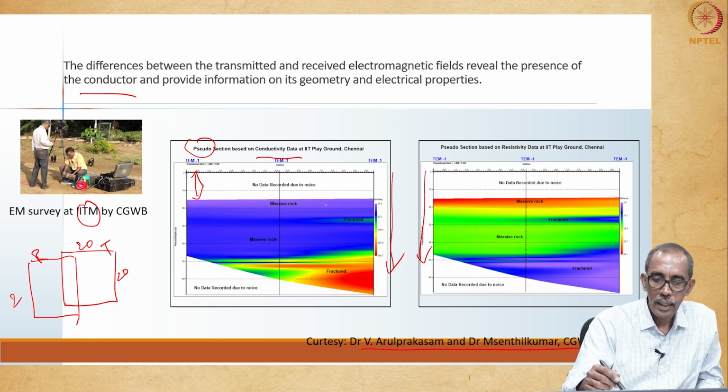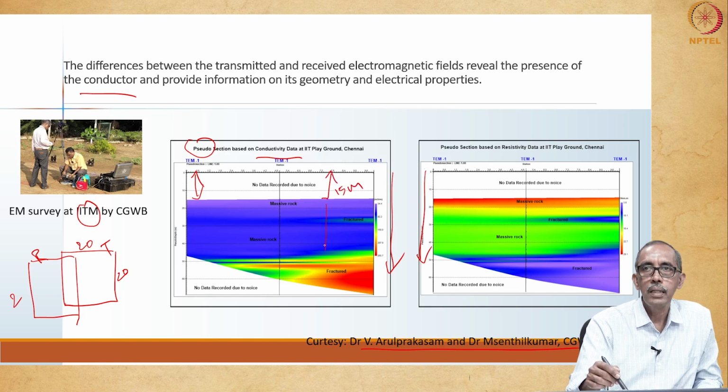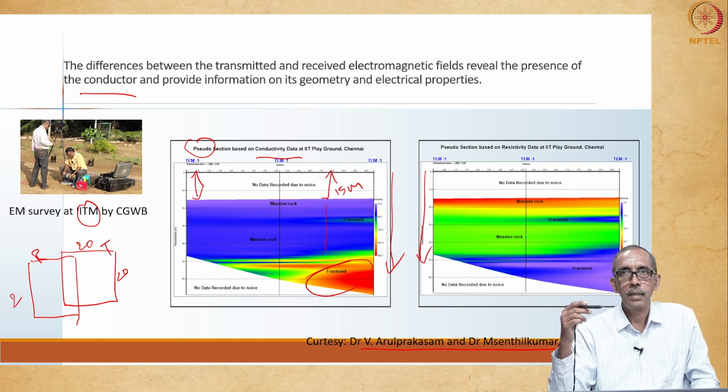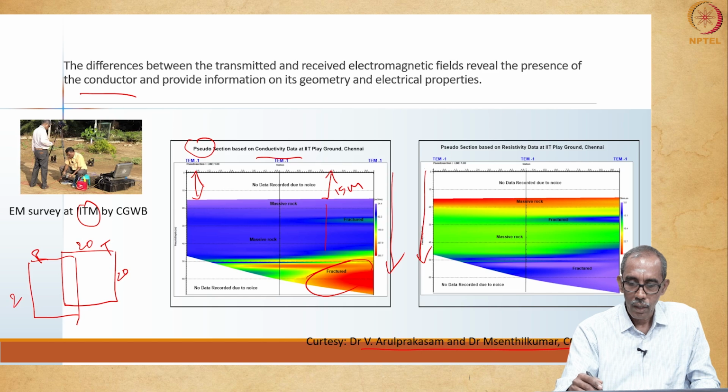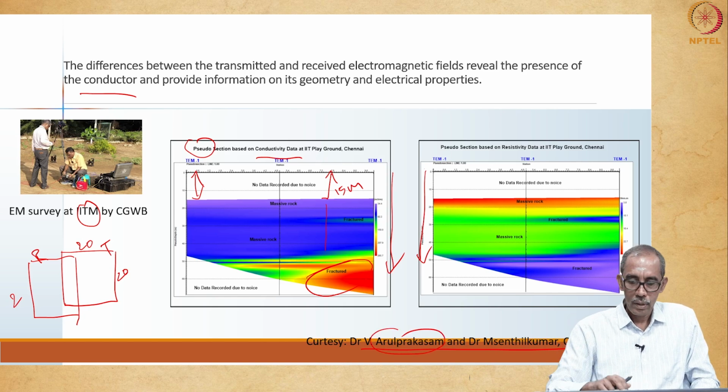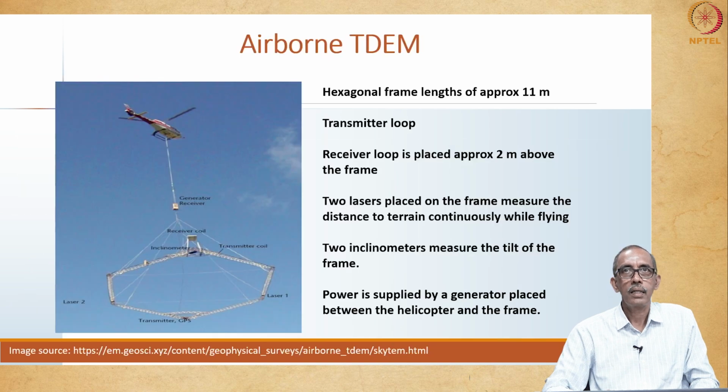And the study indicated we are meeting the massive rock within a depth of about 15 meters, and beneath that the rock is massive continuously. The method also indicates the presence of a fractured zone at a depth of about 50 to 60 meters. This study we carried out recently. We have also requested him to give you a lecture on this particular method with greater details, right.